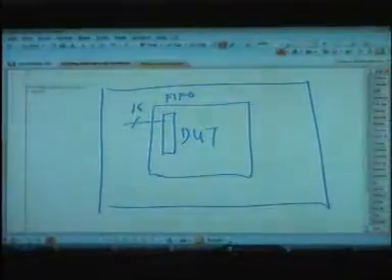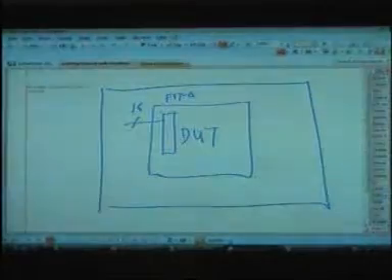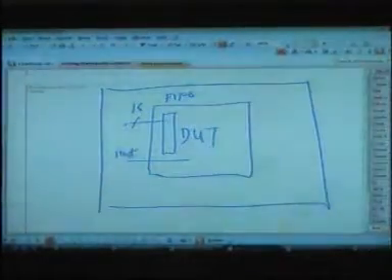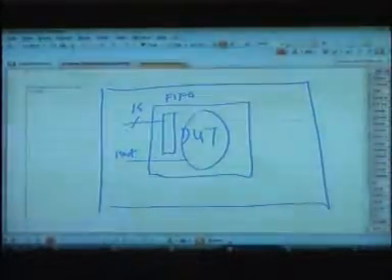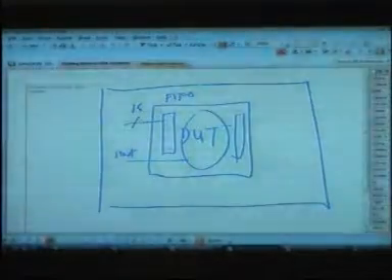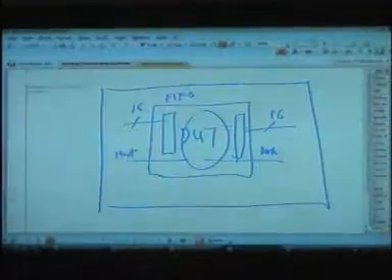I write into this FIFO 128 values, and I say you start, okay, and this is your logic which you have designed to sort this list, and this is another FIFO. You put the result there and you say done, and I have another 16-bit bus and I read all these values, okay?